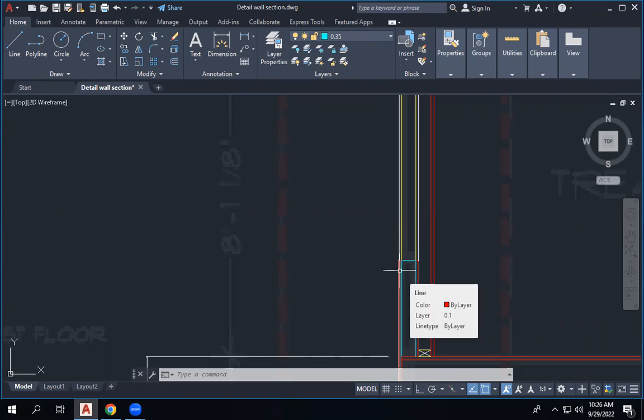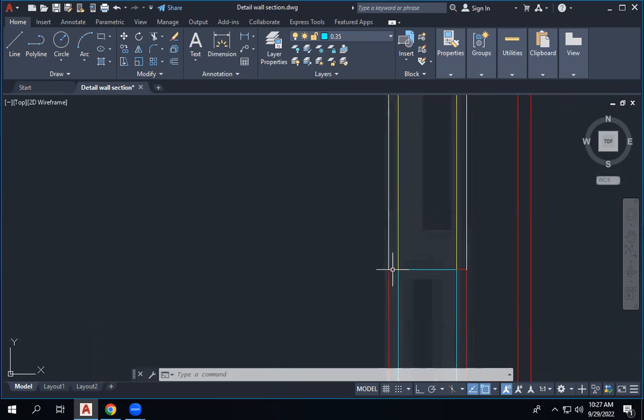Now I'm going to do the sill. You can see also the sill, what they have done here for the windows. They did a little bit projected piece outside on that building for the windows outside. 2-3 inch is coming out. That's also the same thing to avoid the water coming inside. So you will have something here when the water falls onto the surface. They have this one slanted a little bit outside, so the water falls onto this surface, and the surface itself takes the water up to this point, and then like the drip edge, it will fall down.